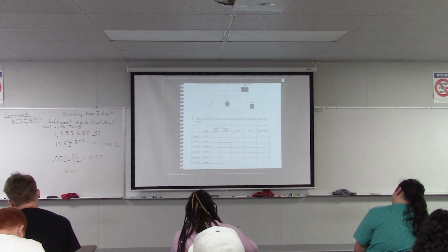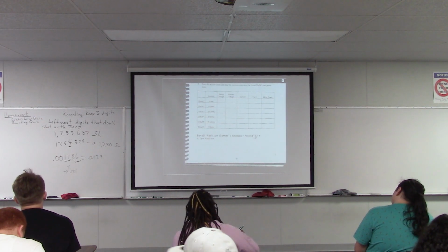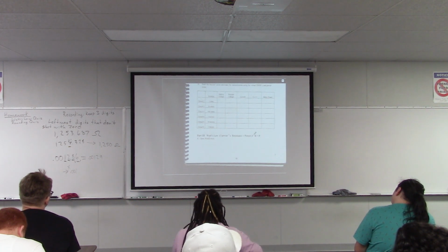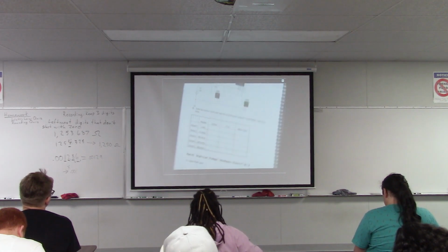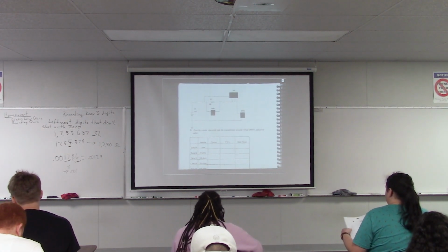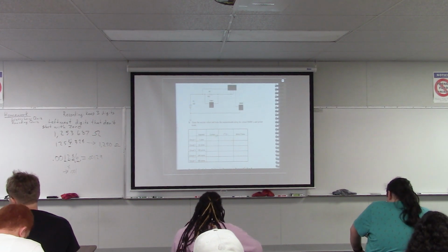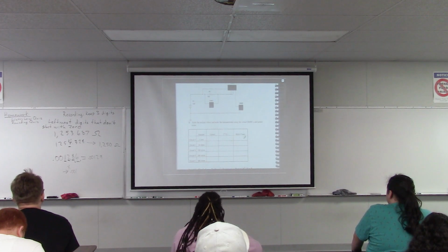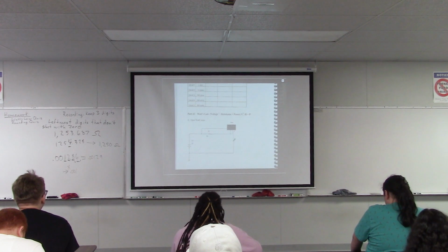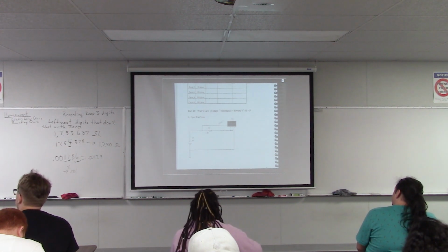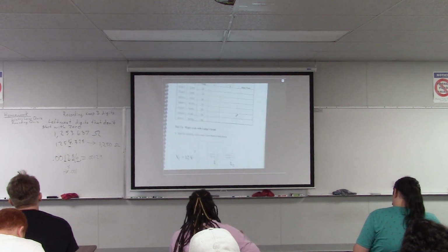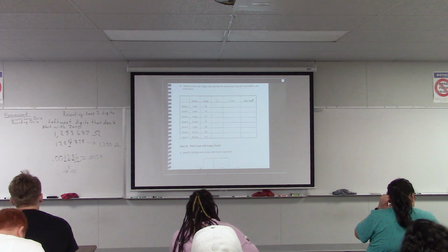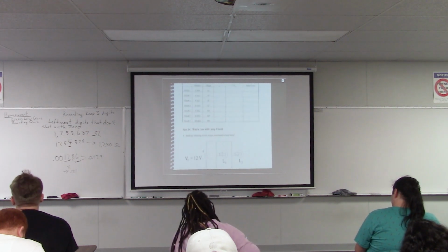So that's the basic form of Watt's law. Down here, there's another form of Watt's law, which is I squared times R. So next, you're going to use this other form, I squared times R. You're going to open a different circuit in Multisim. It's very similar, but in this case, you're going to just measure the current, and you're going to use the I squared times R form of Watt's law and compare that to the meter power. And then down here, you're going to use the third form, V squared divided by R. So you're just going to measure the voltage in this case, and you're going to know the resistance, and you're going to do the calculation V squared divided by R, and then compare that to the meter power. Okay? So that's going to be the Multisim part of the lab. Any questions about that?